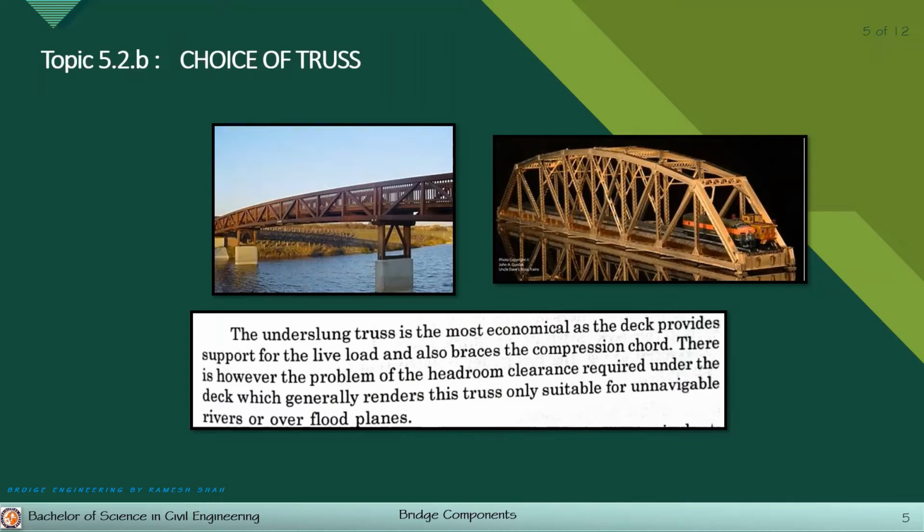So the main purpose of a truss bridge is to have all of its trusses support the weight of its span over time. And if its design is not made properly, there could be some trusses created that have zero force members, which means that they would look nice but they are not working effectively for the entire structure.